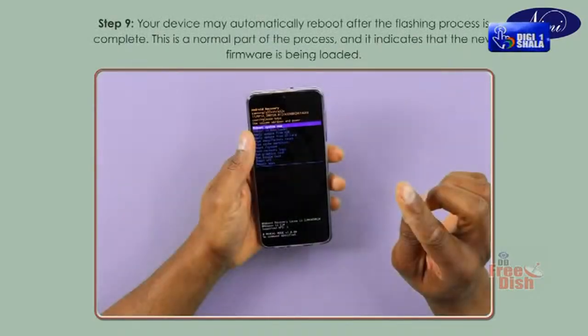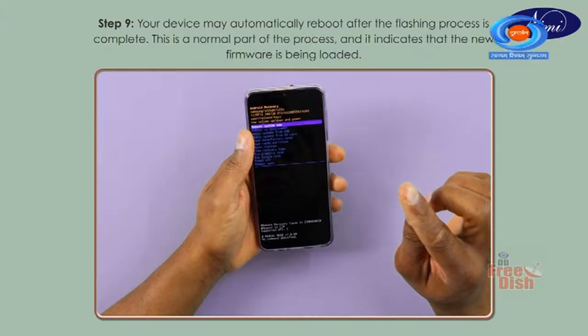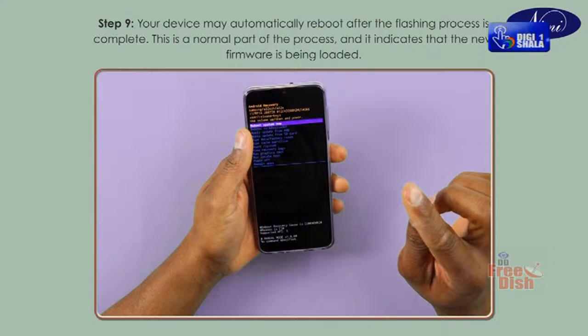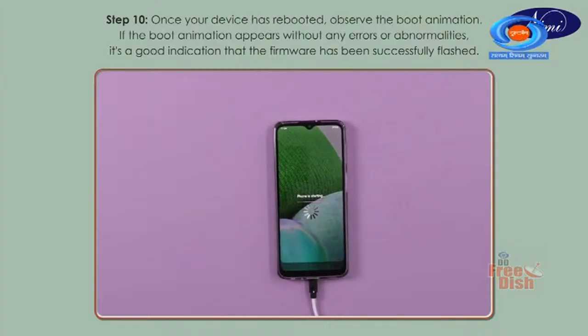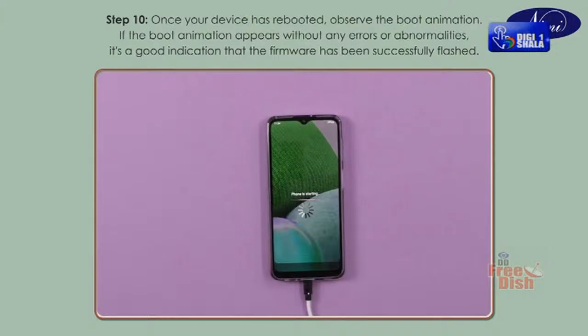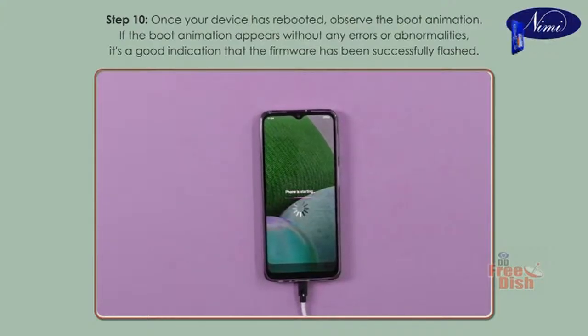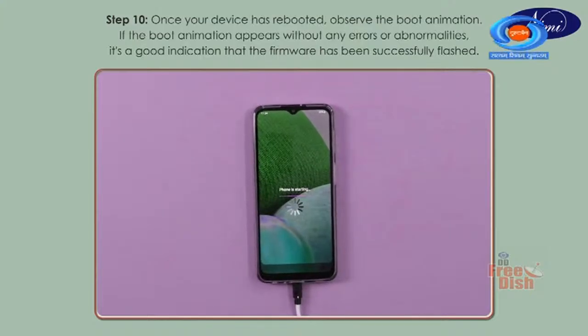Step 9. Your device may automatically reboot after the flashing process is complete. This is a normal part of the process and it indicates that the new firmware is being loaded. Step 10. Once your device has rebooted, observe the boot animation. If the boot animation appears without any errors or abnormalities, it's a good indication that the firmware has been successfully flashed.